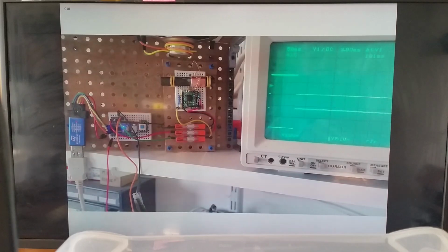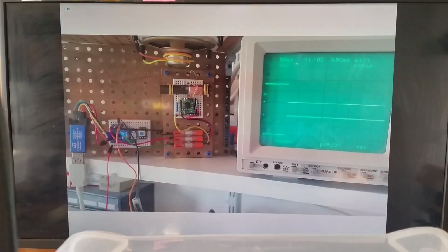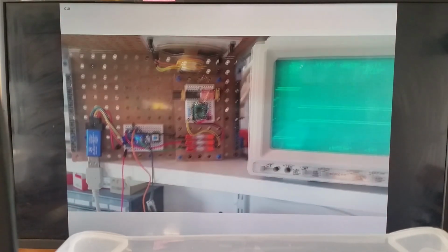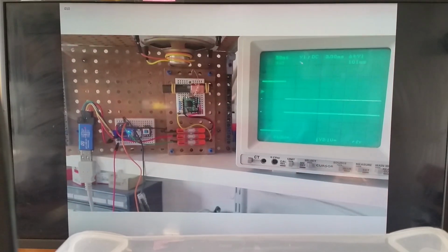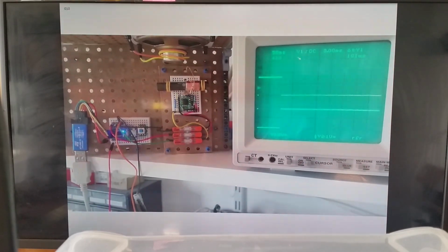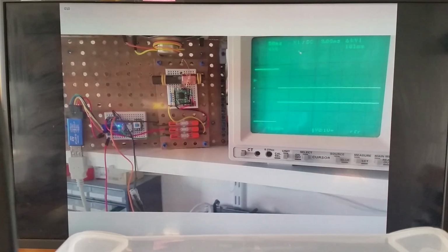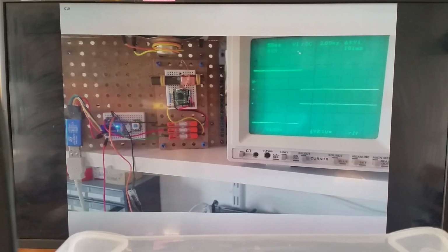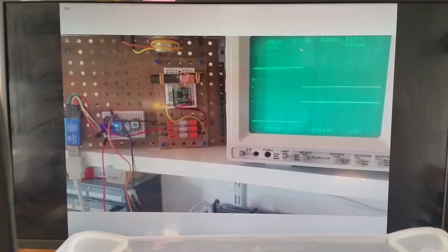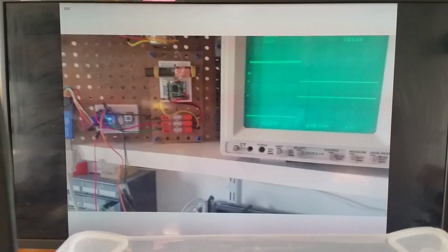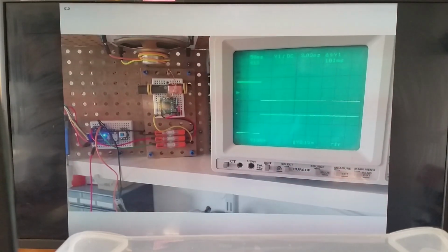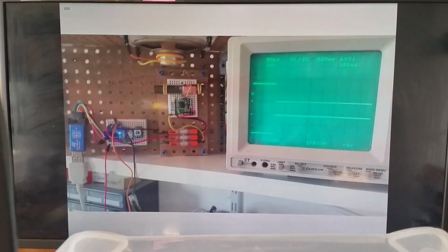That the onboard LED shows an inverted signal is because when the onboard LED is powered on by port pin PB5, there's a transistor, so make it high on the base, then the collector will go low to make the LED light up, and that's the signal we see on the collector. That's why it is inverted.